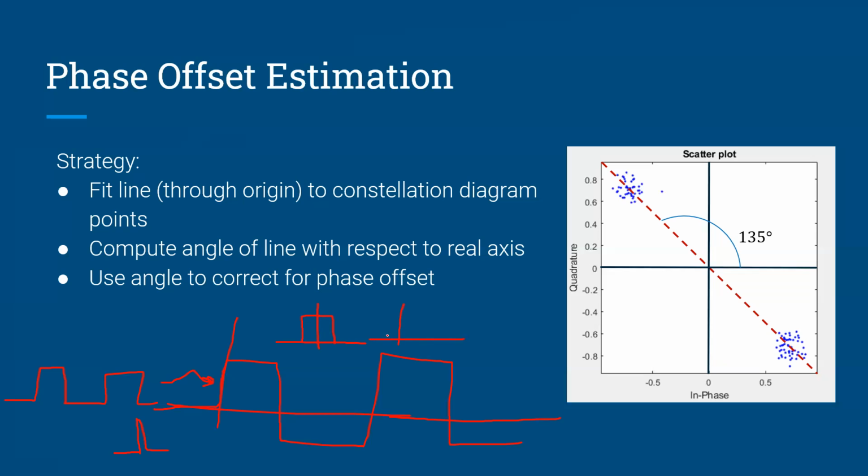Let's say you have two rect functions, and you take the convolution of the two, and the output is a triangle, right? The triangle reaches its maximum when these two rect functions line up with each other. It's a similar idea here. When what you receive lines up with what you expect, you'll have a spike in the cross correlation.